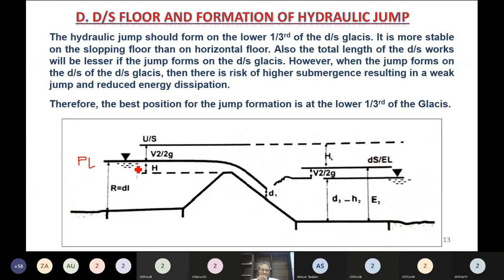Kya bhai? Due to the weir provision, the water level will rise on upstream side. What it is called? Flux, sir. Afflux. Afflux. Yes, good. So it means we know the depth of flow at the design flood and we know the afflux. So if we will add them, we can find the pond level. Okay. So, okay, we can fix that.